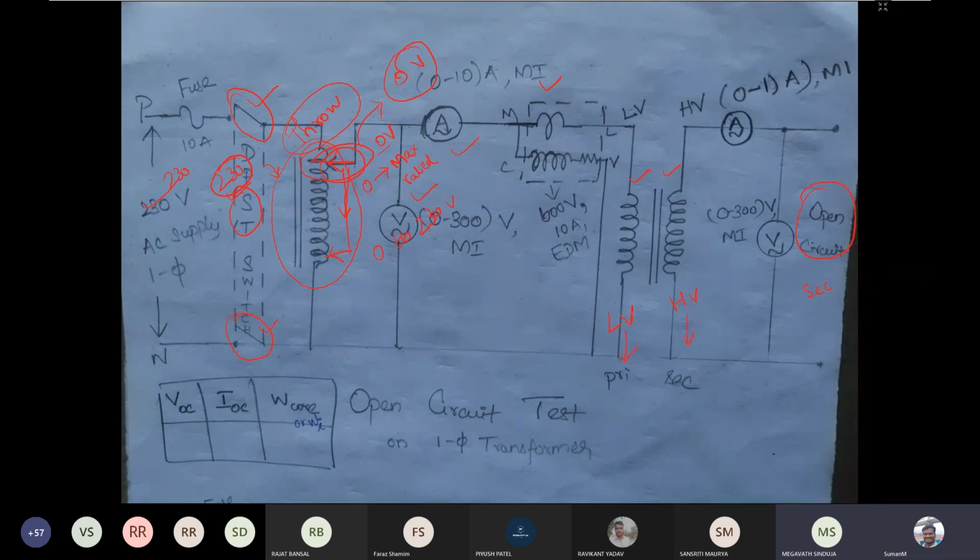But in terms of voltage, let's say the induced EMF on the primary side is 100 volt and the induced EMF on the secondary side is 200 volt. Then the first is considered the low voltage winding and the second the high voltage winding. Here N1 will be lesser than N2. Whichever has more number of turns will have more EMF induced, because the induced EMF is given by N into d phi by dt, right? This phi is constant between the primary turn and the secondary turn. The number of turns is the only thing that changes.